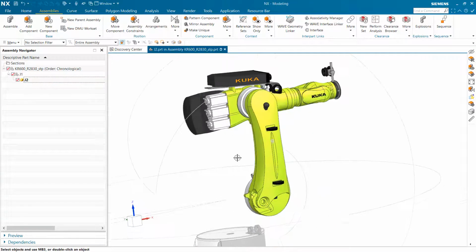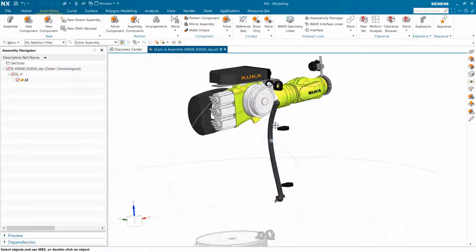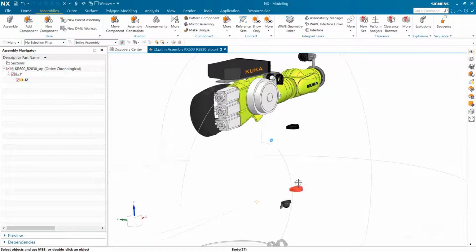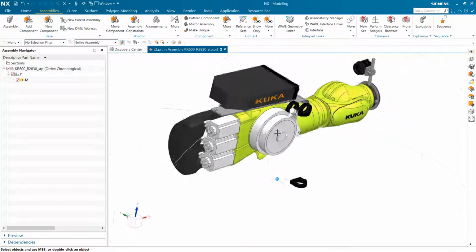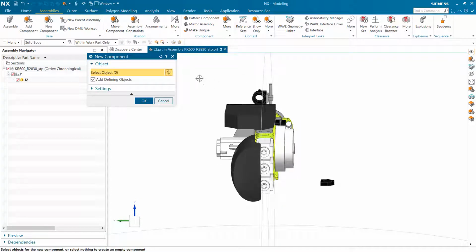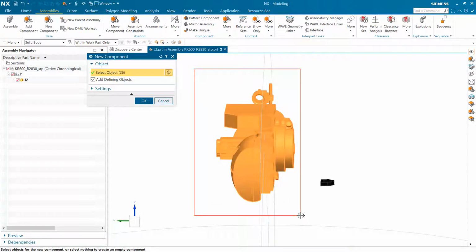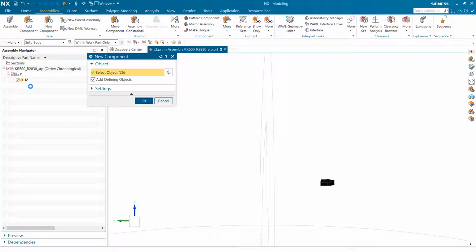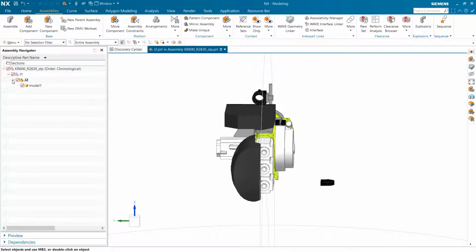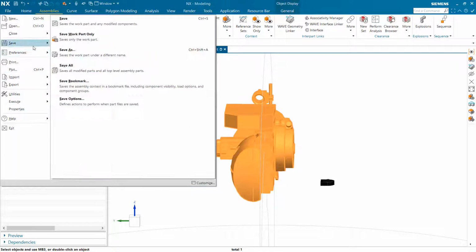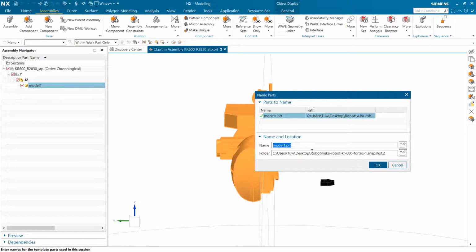Double click. I'll just hide this geometry, and this one I will just remove because those are the flexible components. And here I will have joint number 3 with me, so I'll just click again, separate it out, distinguish the hierarchy, select all this geometry and click OK. Okay, so all this will be saved as J3.